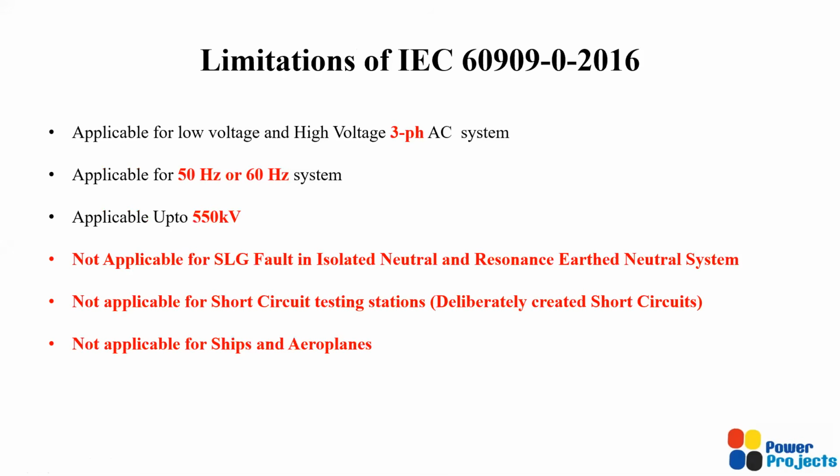So let's talk about the limitations of the standard. As I told, there are ANSI and IEC standards which are globally famous in addition to other standards. Today we'll focus majorly on IEC, not on ANSI, because most of us are working with the IEC standards. This IEC standard is applicable for both low voltage and high voltage, but it is only for 3-phase AC systems. That means it is not applicable for DC, and it is not applicable for single phase systems.